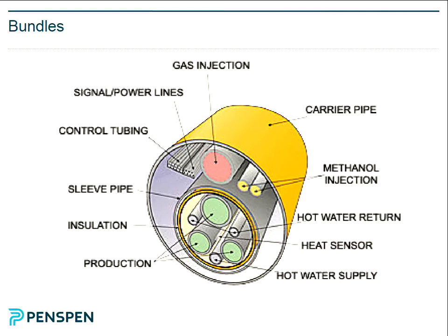It's normally a forged piece, the fitting at the end which all the pipes fit into. So there you've got to join stainless steel to carbon steel, so you have a buffer layer. You need some very careful considerations about metallurgy. On the inside of the bundle, you've got this inert environment. But yeah, you're right, that is something you need to be careful about for sure. So, a lot of interest in bundles, which is good.